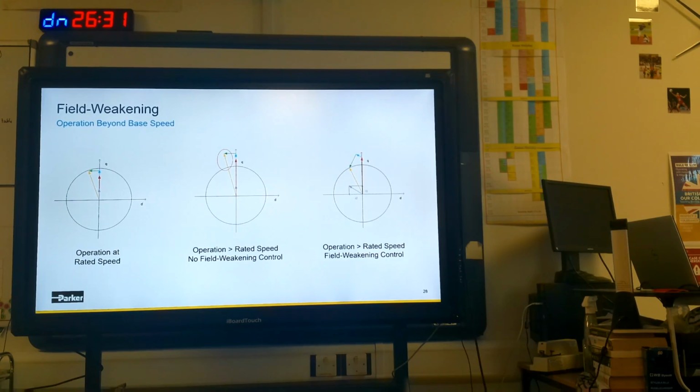And therefore, the torque equation, which basically says torque is proportional to the permanent magnet times the Q-axis current, stays the same even when you're in this field weakening type operation. It's a geometric trick, but it's a very clever one. So in essence, can you field weaken a permanent magnet motor? Yeah, you can sort of, but actually you're not really weakening the field at all. And that has implications.